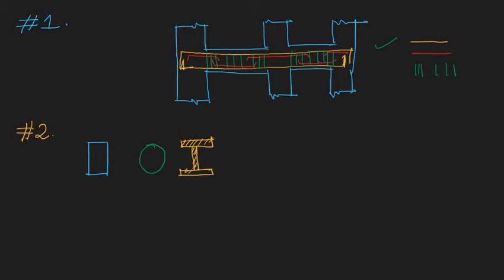And the next question comes directly from this question, that is, why is it best for a beam? I've already discussed a lot about this: it has a flange that takes the bending stress and it has a very good web which caters to the shear stress. That's it, you are done. Okay, again the third question.